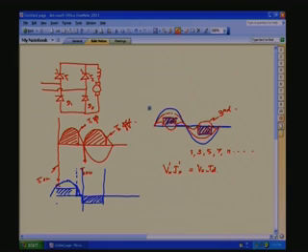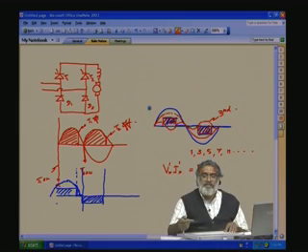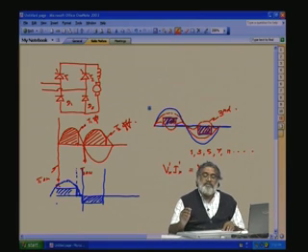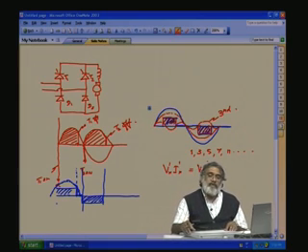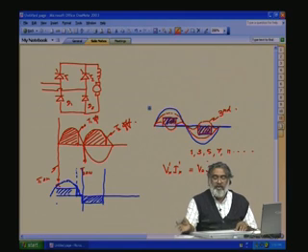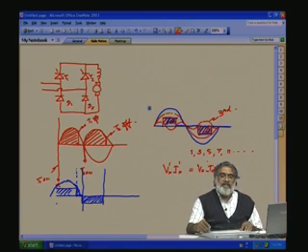But still the harmonics are there. What can these harmonics create? They can also create heating losses, I square R losses, because the power circuit and the device drops. So, it will also consume some power, but it's not useful power, that is not available at the output. This gets wasted in the device.